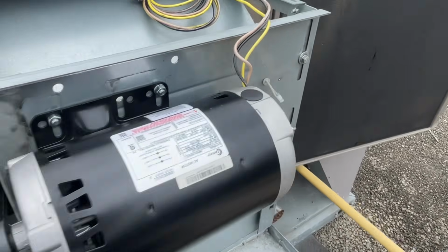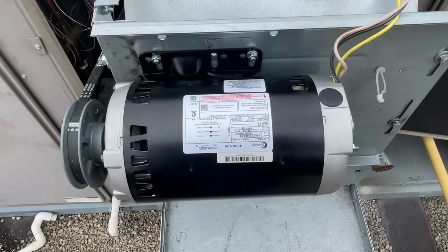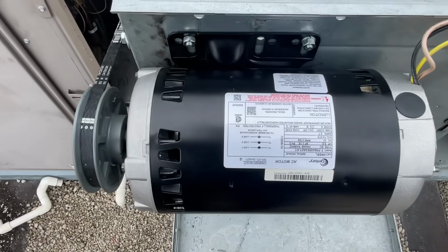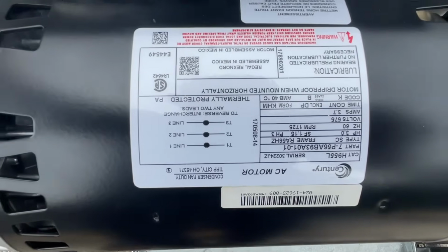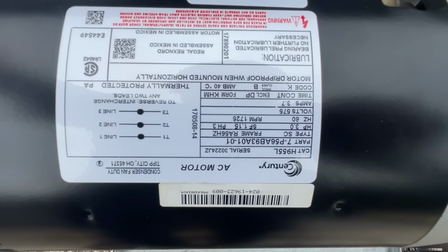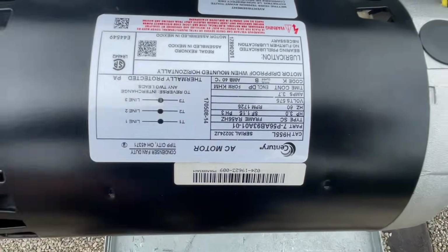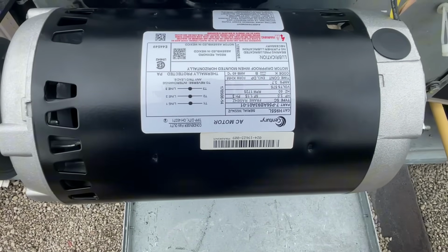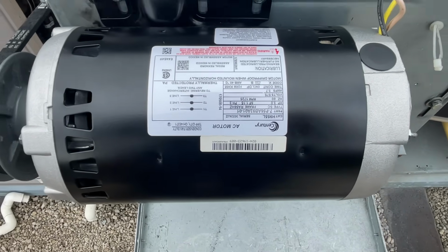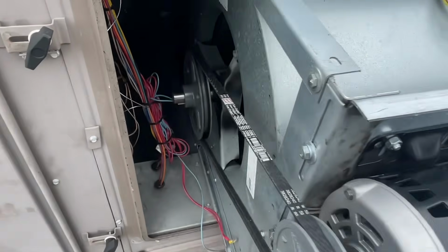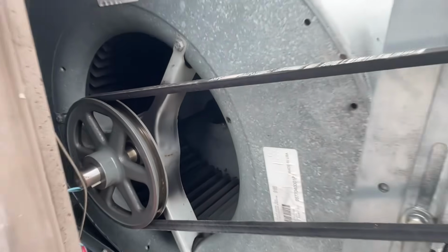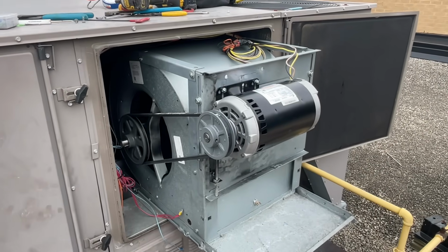All right, so let's check our motor rating plate. And I've actually pulled out the slide again just so you guys can get a clear image of this sticker here. So we're looking at 3.7 amps. And we were running at 3.5 on our highest leg, which is a good sign. We're within our range.